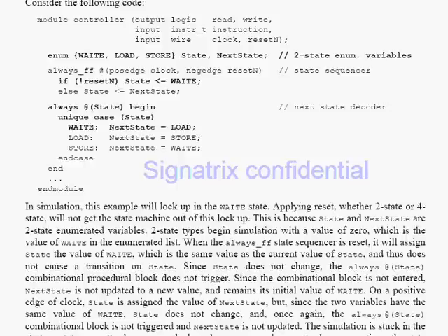Okay, so again you are staying in the same wait state, right? So there is no transition in this; both are in the same state. If there is no transition, this always block, which is waiting for a transition, will never execute, because initially when you start, your state value is 2'b00.